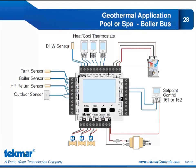So here's my electrical diagram. It looks similar to the ones we went through for snowmelt, except this time instead of a snowmelt control 654, you'll see I have a set point control 161 or 162. And because in this case my pool or spa has been piped off the boiler loop, I'm going to connect to the boil expansion terminals. I still have heat-cool thermostats in case I wanted to do radiant heating and radiant cooling.